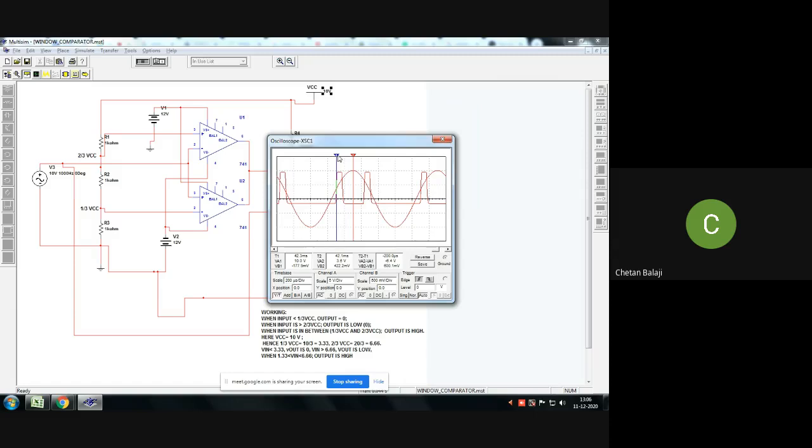Okay, so measure this. 7.2. We are supposed to get somewhere around 6.66. Okay, but I think, yeah, let me arrange. Yeah, instead of 6 I'm getting around 7 to 7.2. Let me be more clear. This is the point where it's coinciding. Yeah, it's 7. So instead of 6.6, I'm getting it as 7. Look at the same point. So it is in between 3.6 and 6.6. Output is 1. If it is less than 3.6 or greater than 6.6, output is going to be 0.